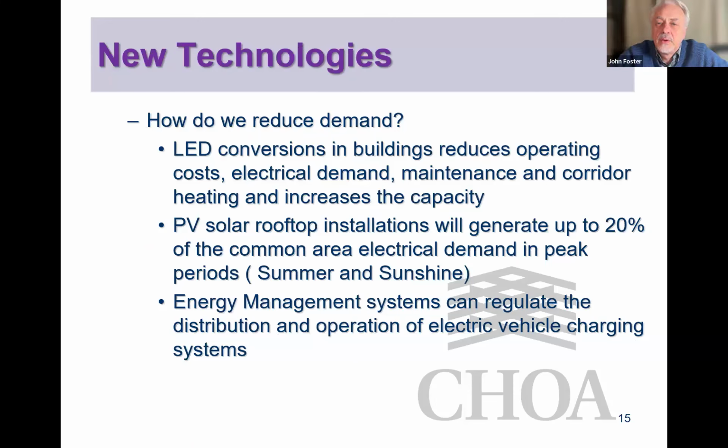Yep, exactly. So reducing demand, we have three different systems that are in use in the province. LED conversions. These happen in mid-rise, high-rise buildings frequently with substantial savings and cost recovery that is in most cases under 2 years. It's a great way to reduce operating costs and electrical demand, and it eases up power for other things in your buildings. A number of buildings that had borderline power to do an EV upgrade for their parking garage did LED conversions and have a substantial amount of power available. So there are some real easy ways of doing this.